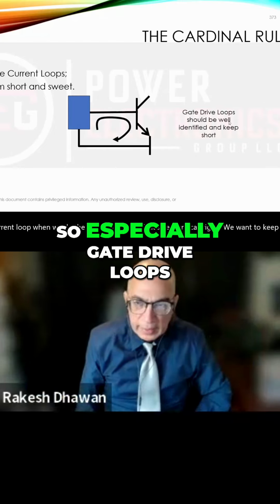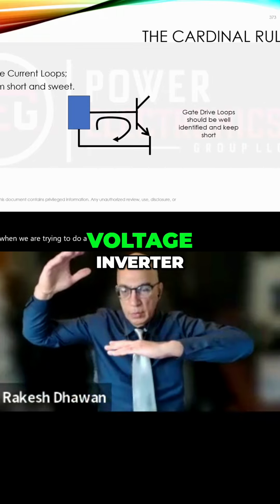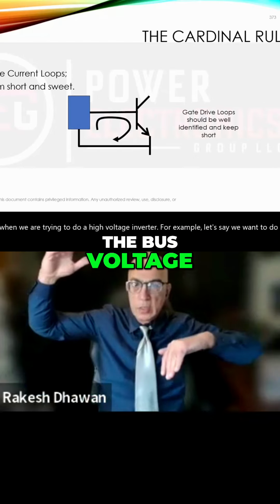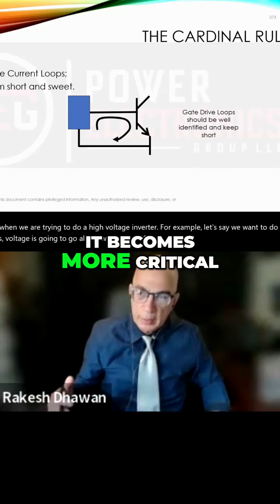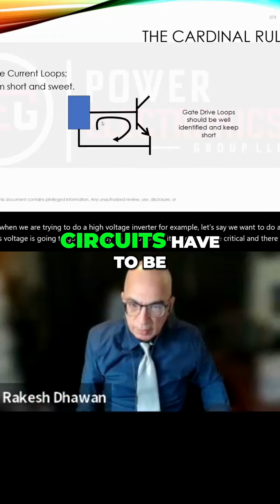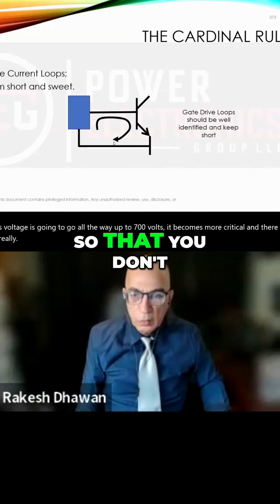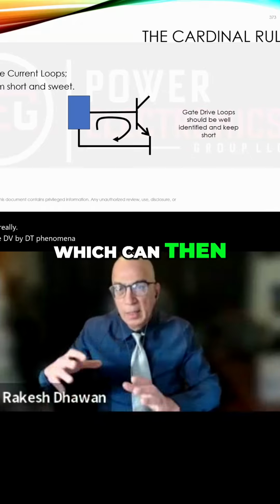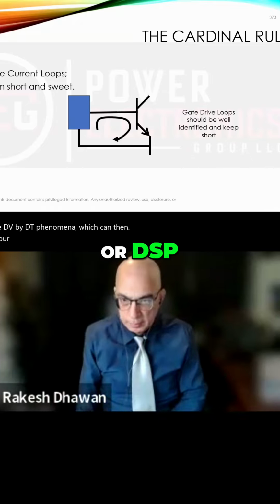Especially gate drive loops, when we are trying to do a high voltage inverter. For example, let's say we want to do a 460 volt inverter, where the bus voltage is going to go all the way up to 700 volts, it becomes more critical. And there, your gate drive circuits have to be really tight so that you don't have dV/dt phenomena, which can then cause a lot of noise into your microcontroller or DSP.